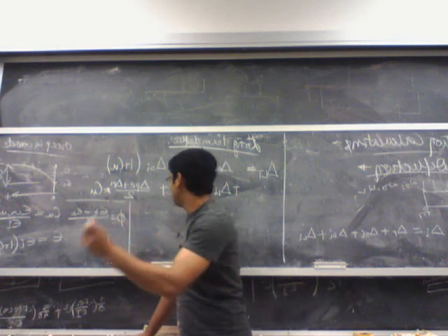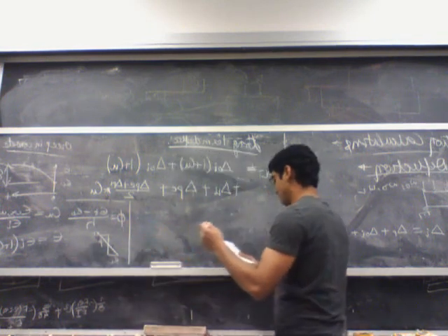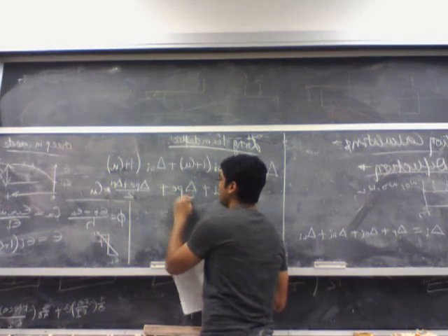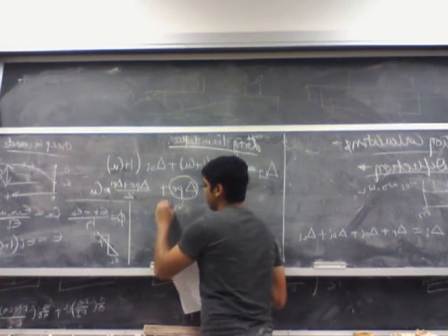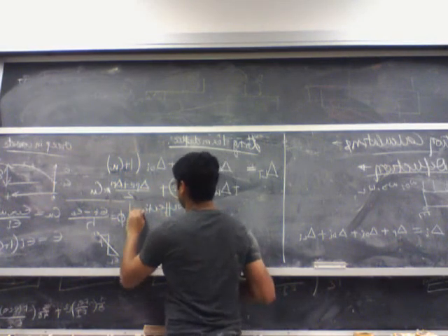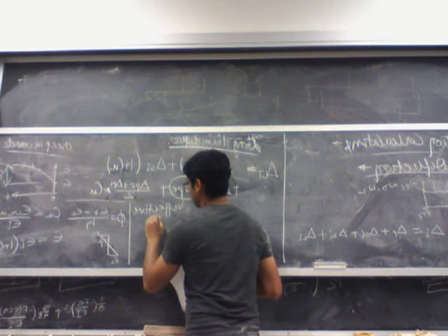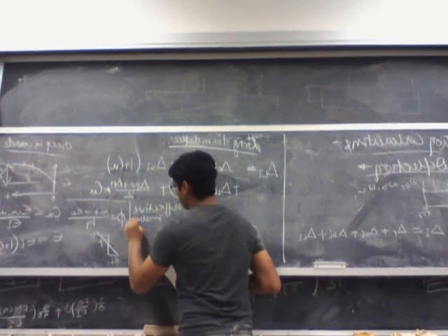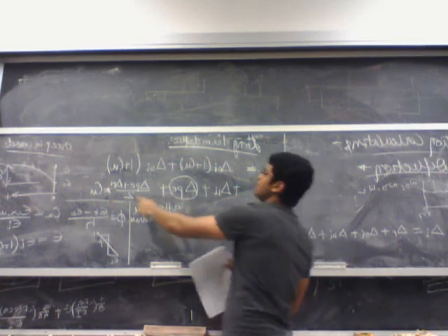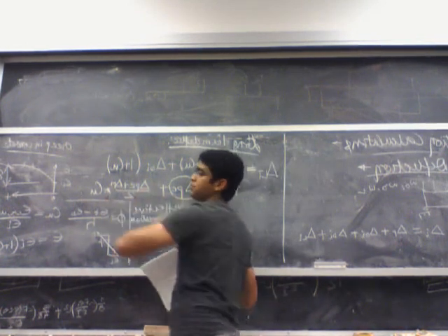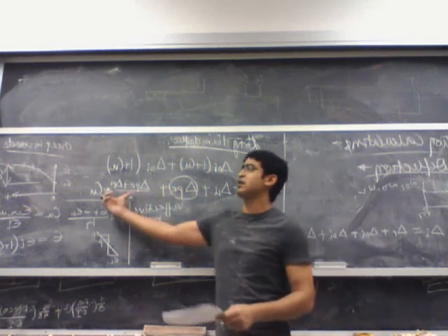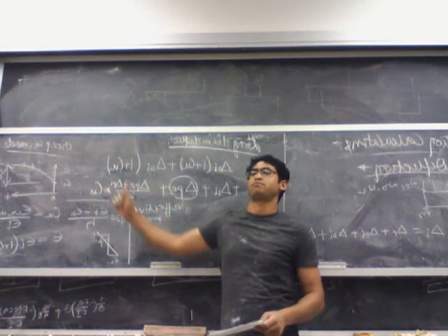I think during the lecture, at least I have an email from Professor Singh in which he said that he might have mentioned it wrong. This is actually due to the effective pre-stressing force, not the initial. So don't use delta Pi here. This is delta Pe, this is the average of the two times Cu. So this accounts for the instantaneous and this accounts for the creep effect over time.